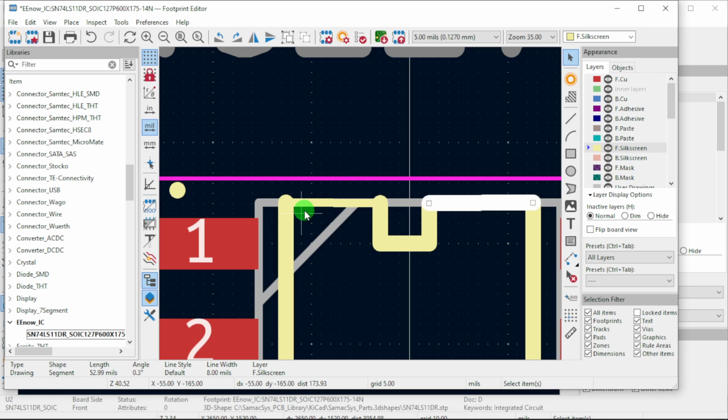I think when I created this project, the design rules are the default. And this is bad. The minimum clearance, no, this is really bad. So you have to change minimum item clearance. It should be at least 6. As a matter of fact, I should do 7, just 7 mils.